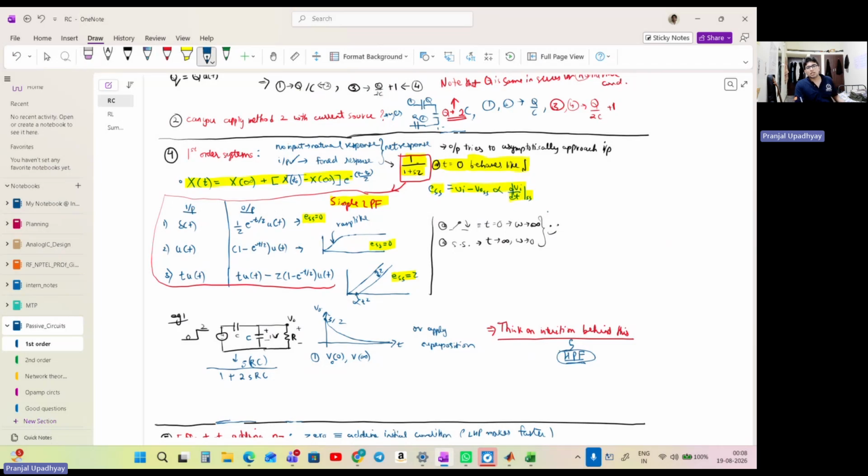We even know that the inverse Laplace transform of this in the time domain is this only, right? So it's quite simple. Then the unit step again is quite simple: since it's a low pass system, it won't allow sudden change. So if I feed a unit step, since this is a very high frequency change, a sudden change, my low pass system won't be able to track this, so it will try to eventually catch up, right? That's the basic idea, and very easily we can also put it out mathematically, right? Then it's a ramp function again.